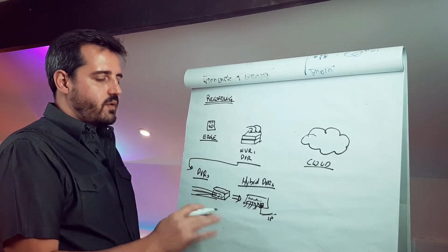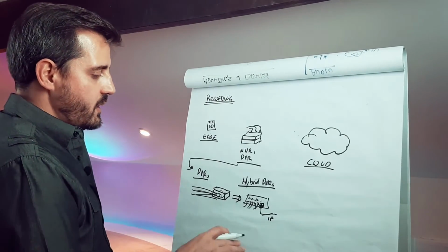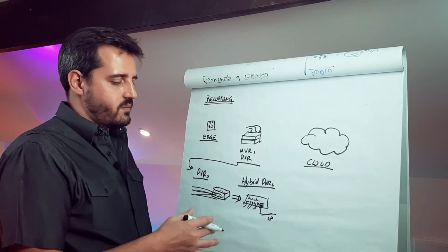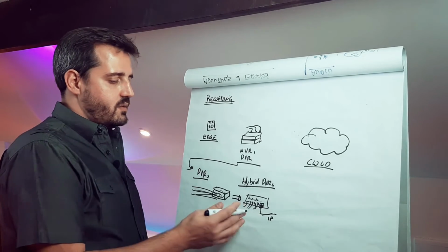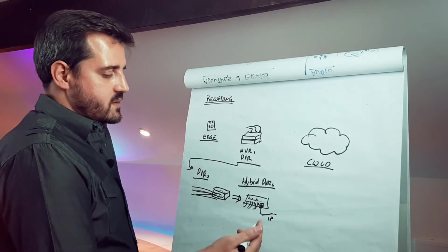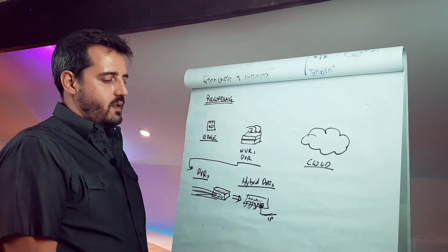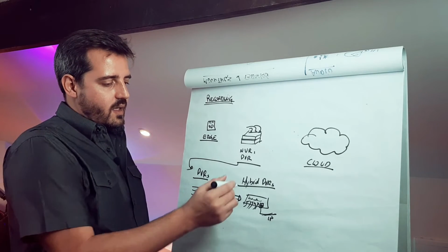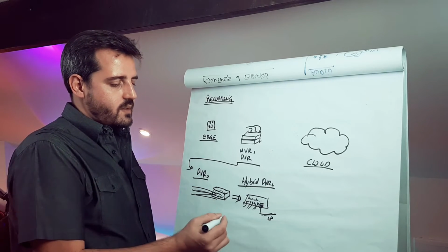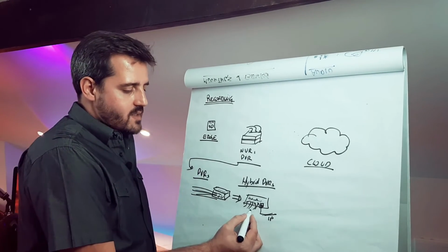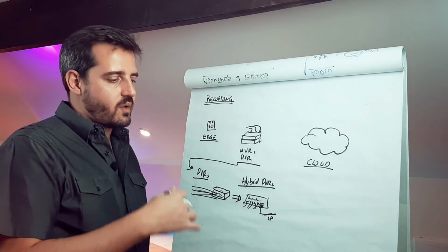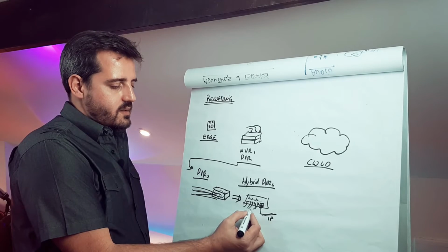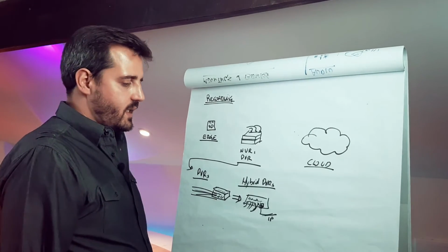Normally, a hybrid DVR will vary from manufacturer to manufacturer, but normally they support about half of the channels of the DVR. So if it's a 16-channel DVR, it will be able to handle 8 IP cameras, because normally IP cameras will be in a higher resolution than the analog cameras, of course. And hybrid DVRs are normally supporting higher resolutions in the coax cable as well. So the high quality analog or HD analog will be able to be used in these hybrid DVRs.